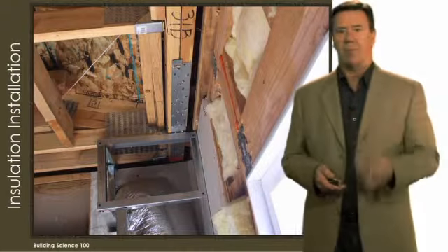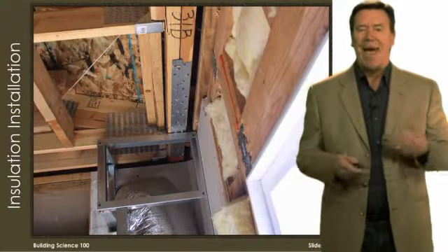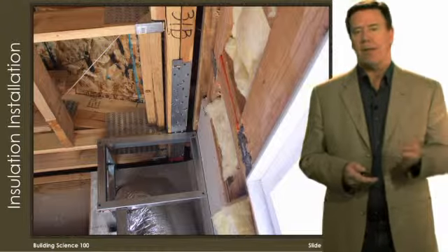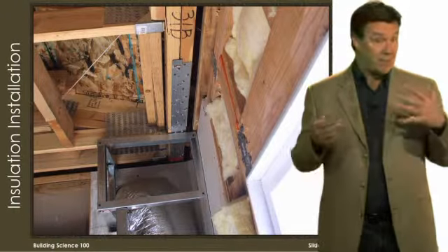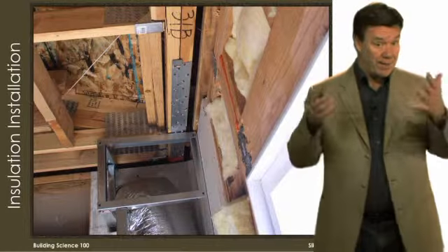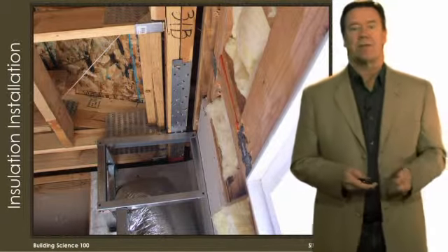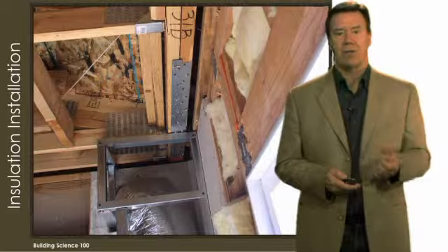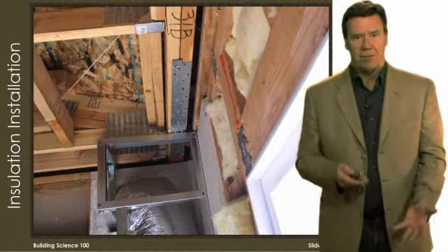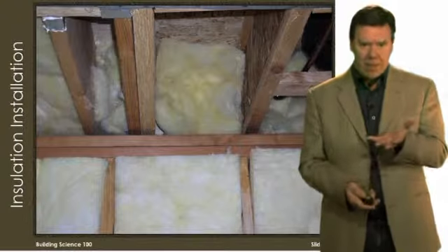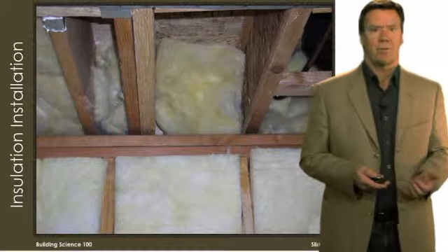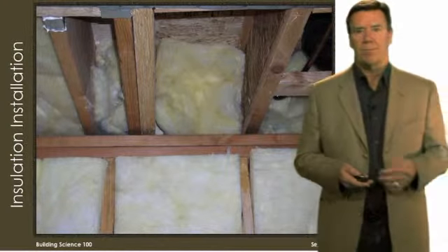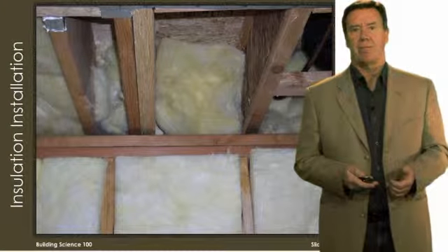Now here's an example of a poor insulation job in an attic. How effective can that be? And I think that's one of the biggest misconceptions in the building industry today, that if you simply put the insulation in the opening, it's going to do its job. But it really doesn't if we don't have an effective air barrier in conjunction with that. So the insulation needs to fully fill the cavity, be in touch with, say, in floors, the bottom of the subfloors and so forth. So it's really important that we avoid these common mistakes that we see.